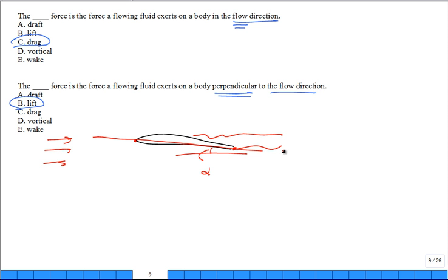It's like, how about if you take that nice foil and try and flow it like this through the air? What do you think that's going to happen? It's not streamlined at all in that direction, right? You took the angle of attack, moved it to 90 degrees. So anyway, you never take it to 90 degrees, right? Unless the airplane's shot down and it's just falling. But what happens is the lift force is still in this direction, and the drag force is still in that direction.